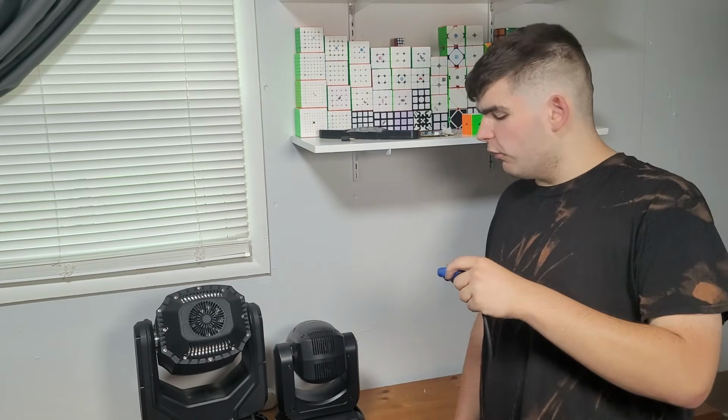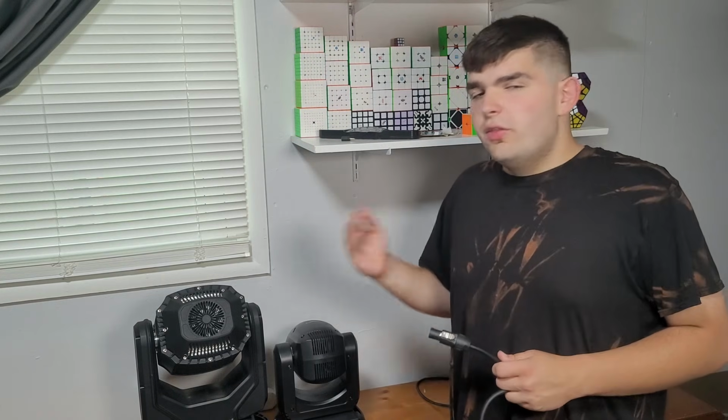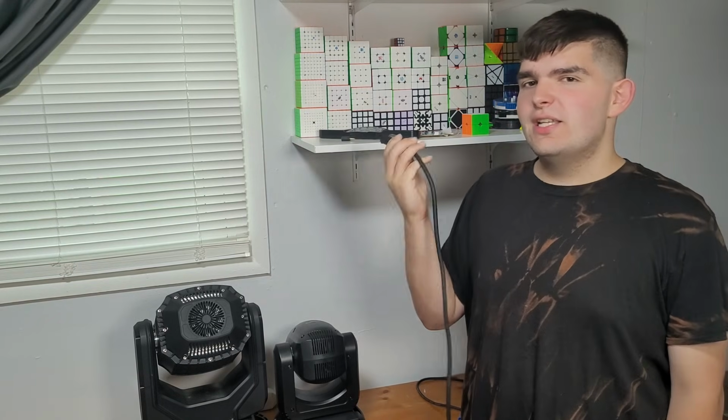If you don't, when you're rotating it to pull it out, it could cause it to arc inside and completely fry the moving head and even start a fire. So don't do that at all. The bigger, more expensive moving head is using the black, newer power cons. It works the same way where you rotate it, put it in, and twist it to lock it, but these are safe to take out if power is connected.